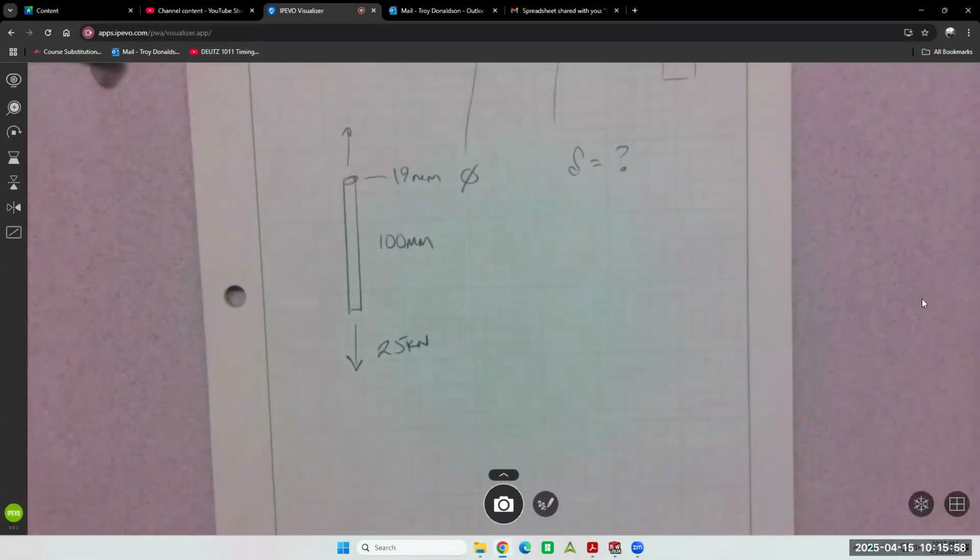Before we do it, let's go back over the concept of how we get to deformation. We first check the stresses. You did that. The stress is good. It's within the limit. If it's not within the limit, you cannot calculate a deformation. It's not predictable. If it's within the stress limit of the material, then it is predictable and we can calculate it.